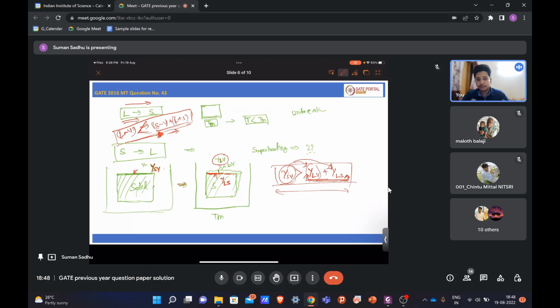If you put one gold sample inside the furnace at the exact melting temperature, that is 1064, after some time you will see that your gold sample has melted. But if you put a liquid gold sample inside a furnace at 1064, it will stay in the melted condition only.